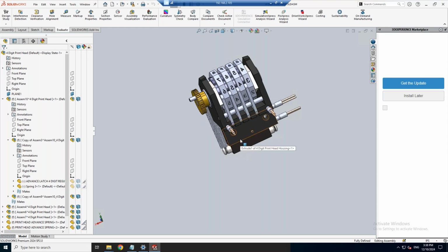But now that I've updated this model in SolidWorks, I need to then go into XA and update the bill of material and the parts and the operations and routings in general there as well, to make sure that shop floor and production also have what they need to actually build the product and ship it out to the customer. So instead of doing a manual data entry process or exporting this to Excel and then importing into XA and massaging it, I'm going to use CADLink to do that for me.